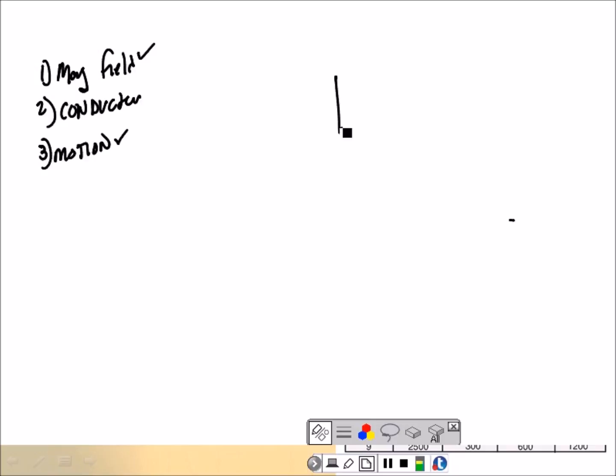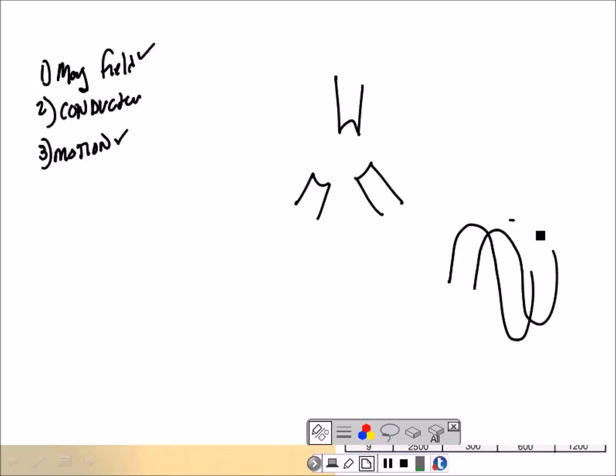So if I've got a 3-phase motor, and then these poles, I'm not drawing all the poles. So if this is the north, I've got a pole over there, right? But how does 3-phase go? 3-phase goes like this. Now notice when this guy here starts dropping down, what is this guy over here doing? So if I call this phase A, this phase B, and this phase C, then automatically when phase A starts going down, phase B starts building up. And what it does is it makes the magnetic field do what? Shifts.